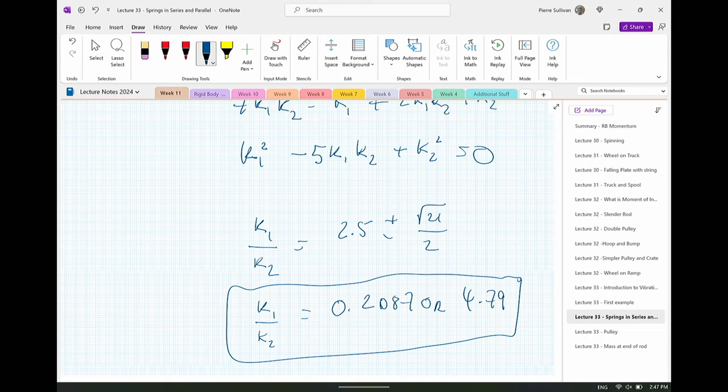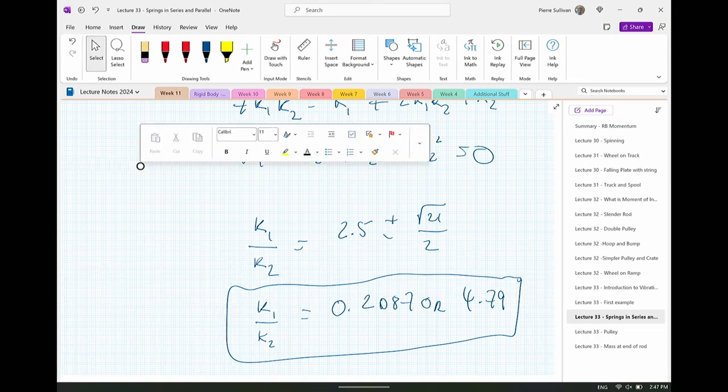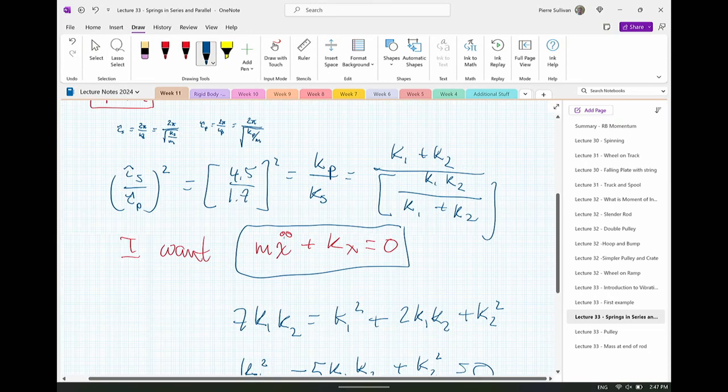You can solve through for all of this, but ultimately, the cheaty bit here is that once I have it in this form right here, I can solve the whole thing. Once I solve the whole thing, I'm done. I just am looking to set up the equation in one form, m x double dot plus kx, and never ever have a negative term in that equation. Good? All right. Let's try another example.